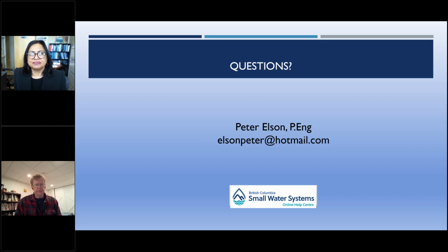So again, I would suggest they're looking for you to come up with a plan to let them know where you're testing and how often you're testing for that, so that you can track any change in the amount of manganese in your distribution system, which is the whole point of doing this data collection. But if you've got a well, which I'm sure you do, because that's where manganese comes from, you want to be checking your source as well. Make sure that you're consistently monitoring the manganese actually coming out of your well, because that'll help make sure you don't get blindsided by an increase in manganese at some time in the future. But I think that's probably what they're after, some kind of testing schedule.